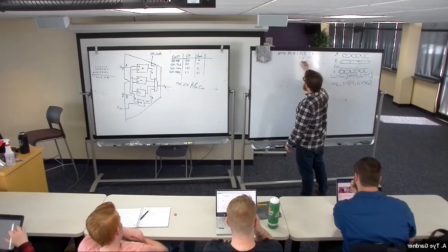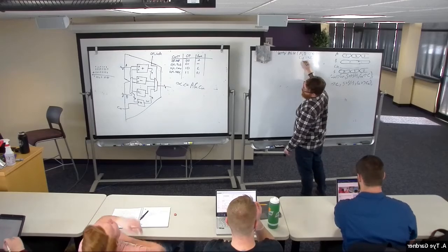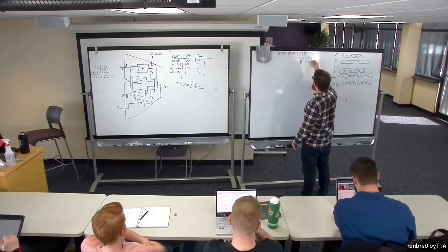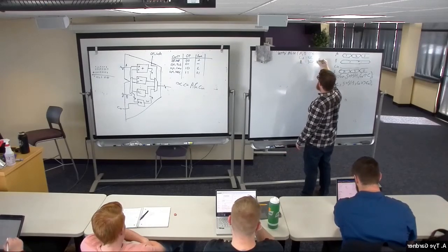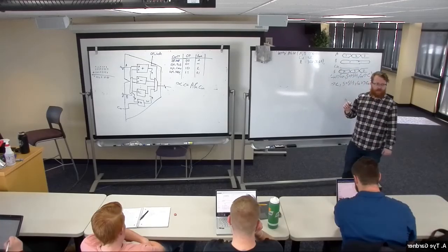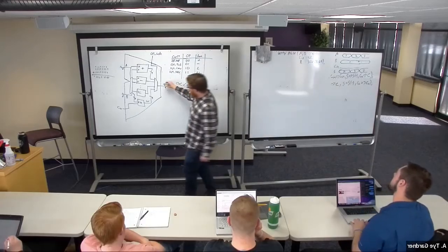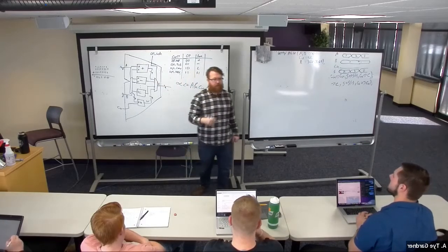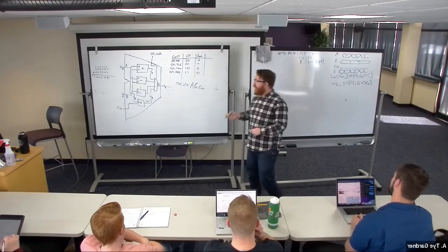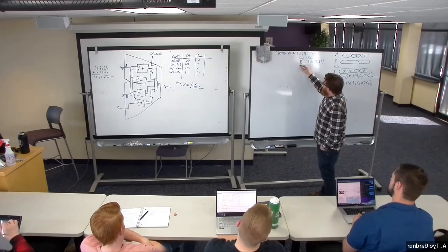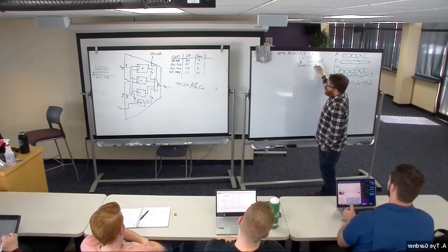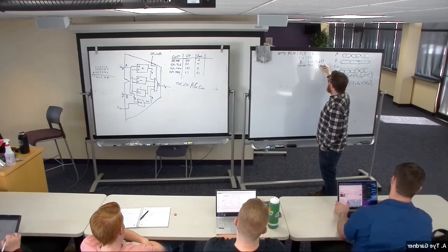And out, I haven't named it anything. Let's call it R for results, which is a standard logic vector that is going to be 8 down to 0, because that's how big the result is. That's R. It's 9 bits. 8 down to 0 is 9 bits. Okay. It also needs opcode, which is a standard logic vector of 1 down to 0.